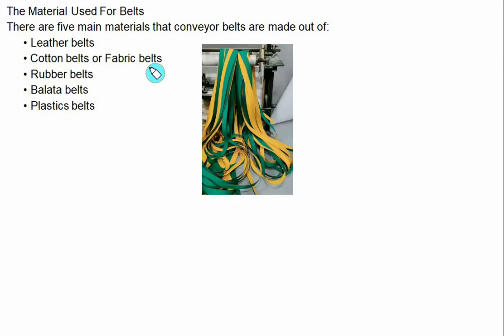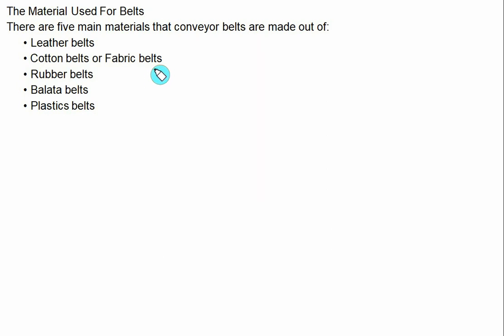Most fabric belts are made by folding 3 or more layers of canvas or cotton duck and stitching them together. These belts are also woven into a strip of desired width and thickness. They are treated with linseed oil with some filler to make the belt waterproof and prevent injury to the fibers. Cotton belts are inexpensive and suitable in moist climates and moist environments. Since cotton belts require little attention, they are mostly used in farm machinery and belt conveyors.